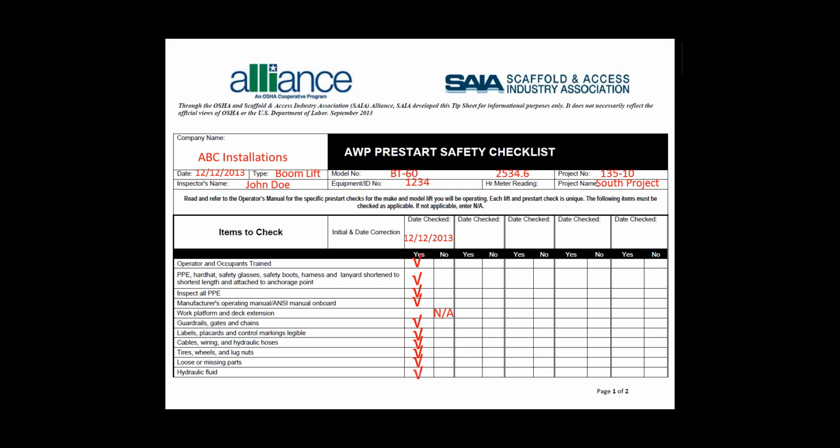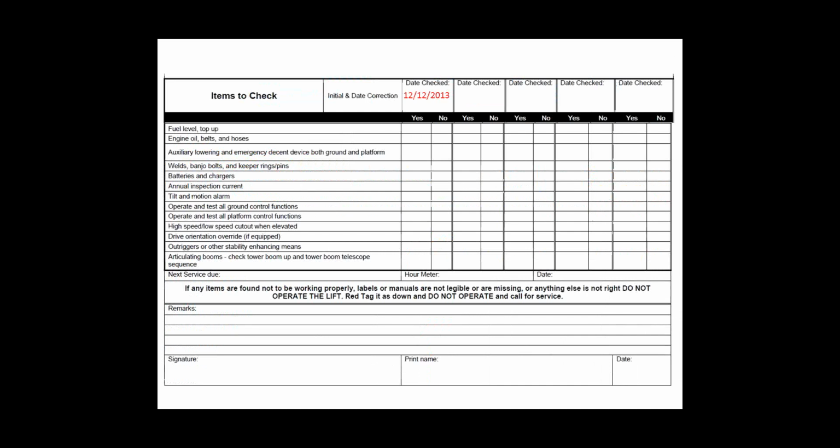We want to make sure that the machine has appropriate hydraulic level in it. And different machines are checked in different conditions, but generally speaking, the hydraulic oil needs to be checked with the platform fully stowed, or the boom fully lowered, and any outriggers or stabilizers or other devices are fully retracted. Otherwise, you may assess the oil level being low and accidentally overfill it.